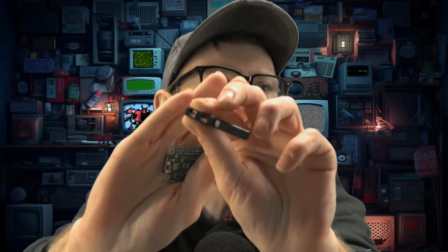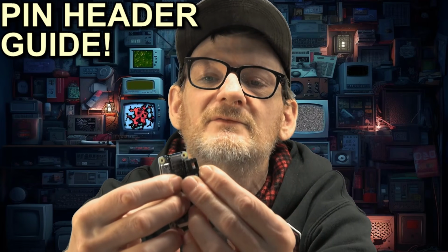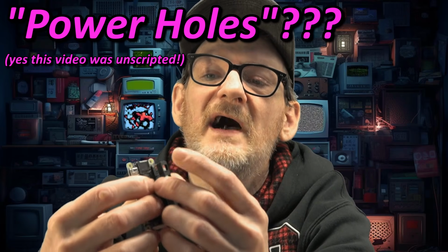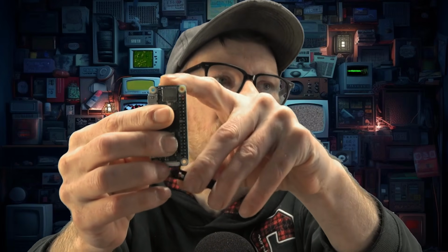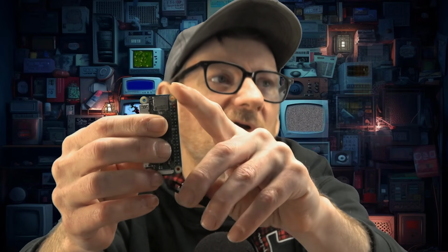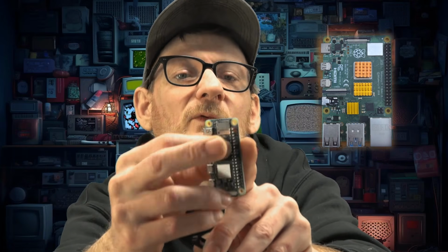Along with this, whichever variation you get, you always get my new header pin adapter cover thingy. I don't know what I'm calling it yet, but if you line it up this way, make sure that the power holes there, that's so you can connect a fan to the 5 volts if you want to, but make sure that lines up with this side of the pin header. Now, on a Pi Zero, the SD card is right up here on the top, but on a Pi 4, it's going to be over here. But this is still going to be on, from your point of view, the top right of the board.